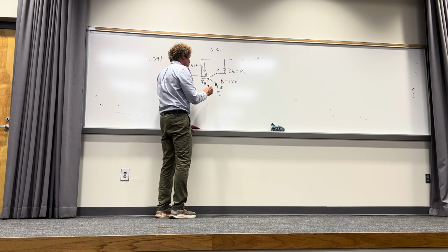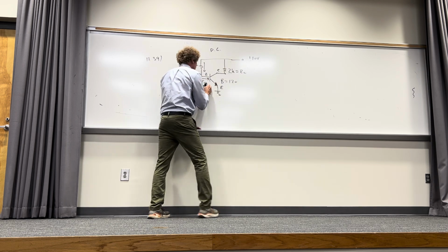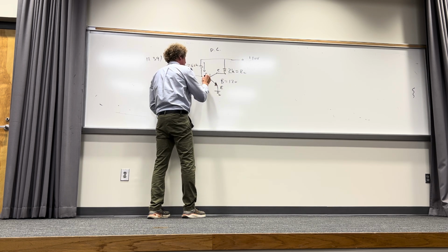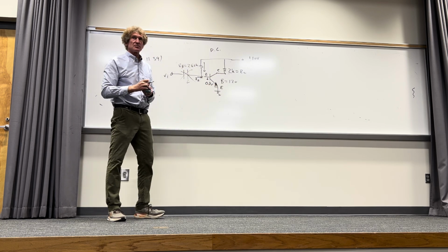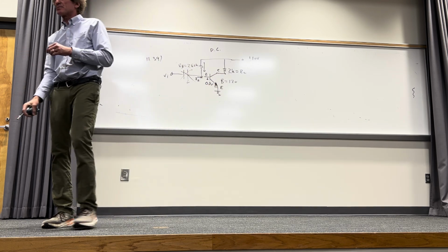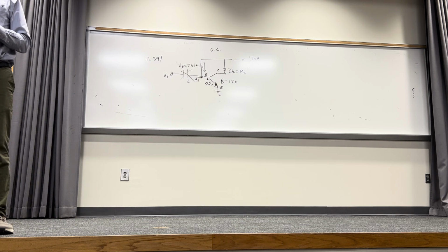if you've got 10 volts there, you're going to get a voltage drop. I've got to give myself a little more room. We're going to call this IB. You're going to get a voltage drop plus to minus 0.7 volts for a silicon transistor, which is 99.9% of all the transistors in the world today.